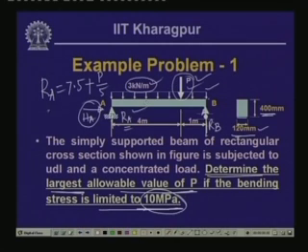Now, Rb correspondingly will be 3 times 5, which means 15, plus P minus 7.5 minus P by 5. So, Rb consequently will be equal to 7.5 plus 4P by 5. So, these are the values of the reactive forces Ra and Rb.